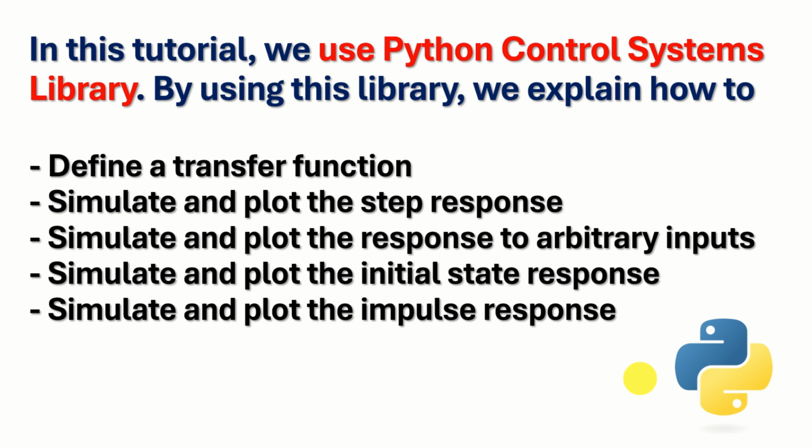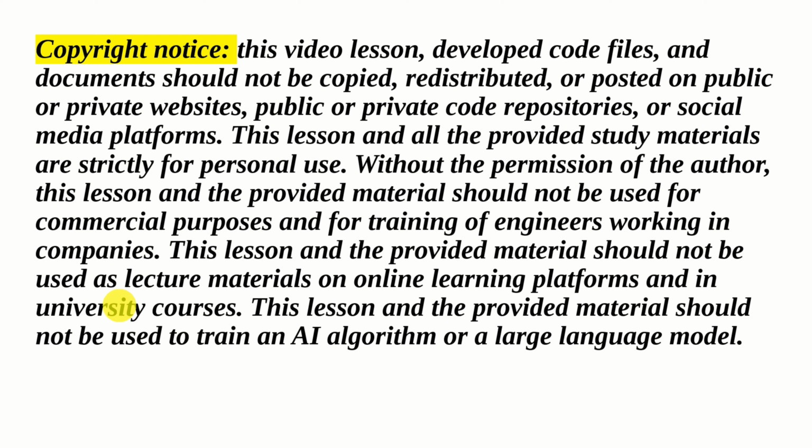By using this library, we explain how to: Number 1. Define a transfer function. Number 2. Simulate and plot the step response of the transfer function. Then, how to simulate and plot the response to arbitrary inputs. Then, how to simulate and plot the initial state response. And finally, how to simulate and plot the impulse response.